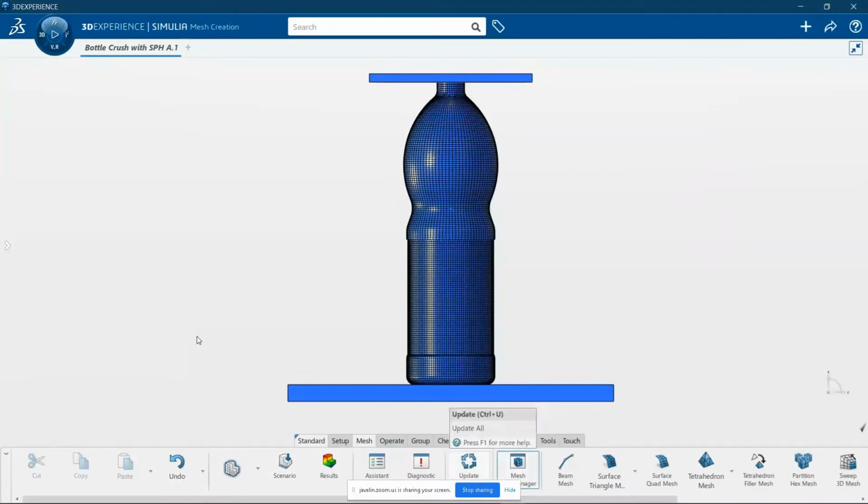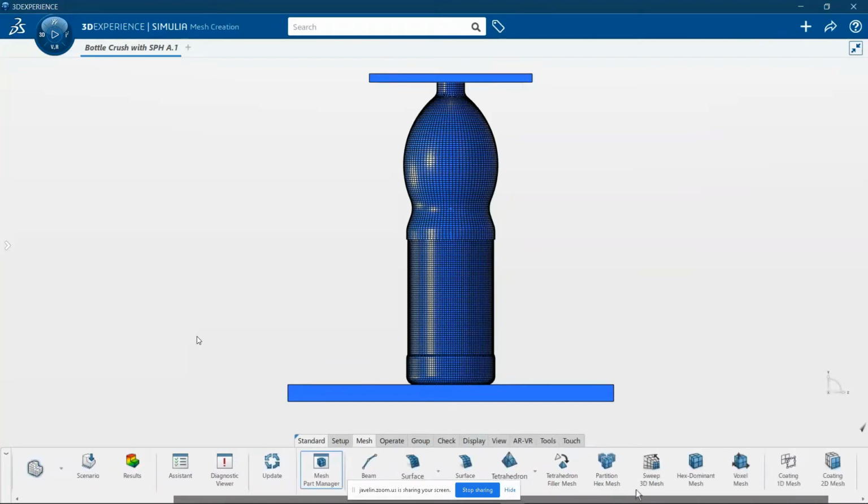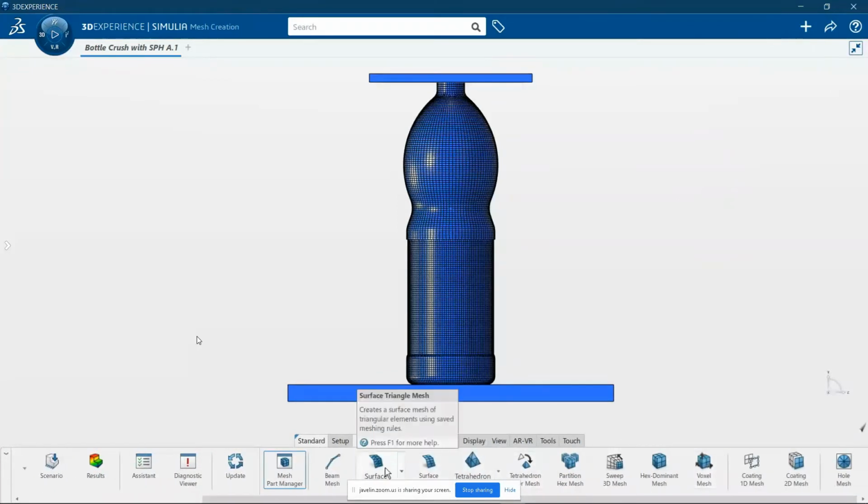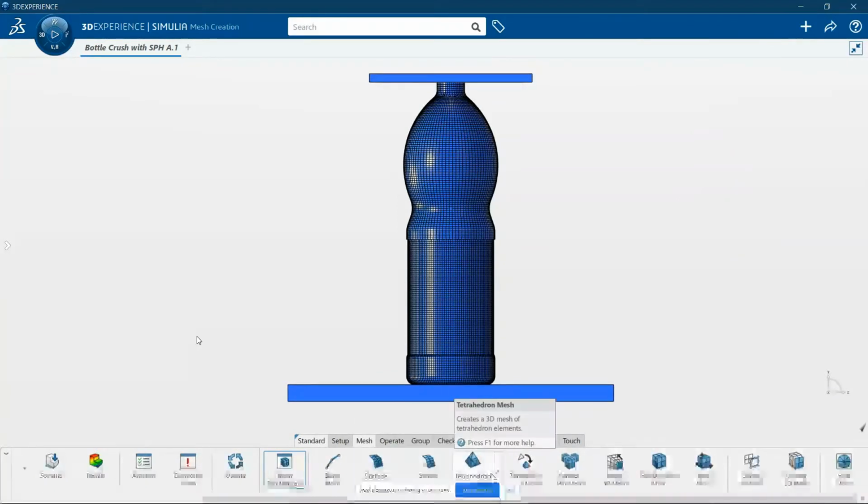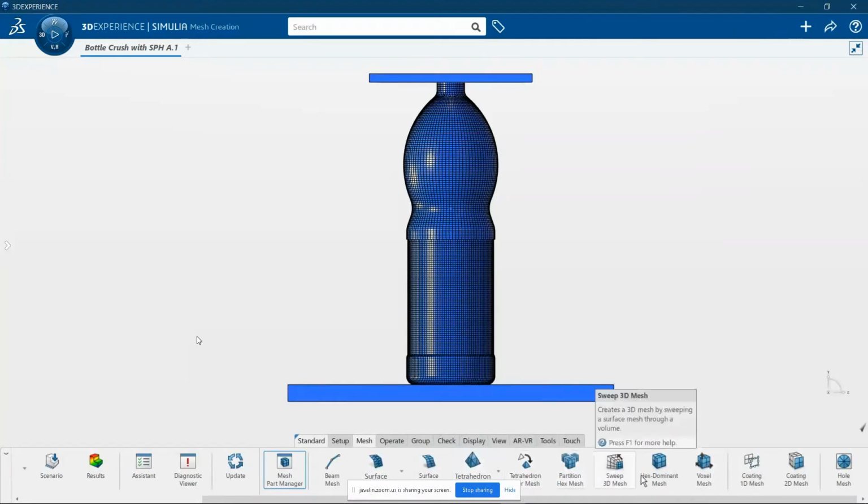So that's the mesh that's being used. You don't see the vertical on the top and bottom because I'm using shells. So it's only the top face of the bottom part and the bottom face of the top part that are meshed. You can see what another nice thing is now, we've got access to different element types, right?